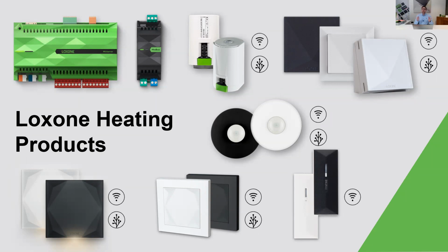As always, we've got the Miniserver on there. The Miniserver brains the system and is required for everything we do. Functionally, within the Miniserver there is a product that we would very commonly use for heating controls: the relays. Just like a wiring centre on a normal heating system, we need to be able to trigger certain products on our physical heating to turn on. We need triggers for the boilers, pumps, zone valves, hot water cylinders, and anything else we may need to trigger on this system. Typically, those are going to be relays.